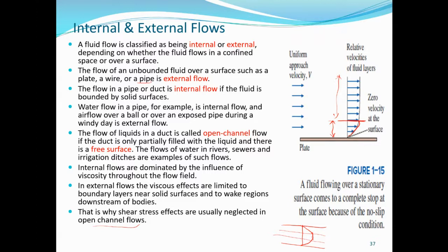So the internal and external flows more or less can have, let's say, pipe flow and open channel flow. Open channel flow is an external flow. And like I mentioned here, if the pipe is not full, you can have flow in which the pipe is not full. This is also treated as open channel flow, because you have a free surface of the water body.